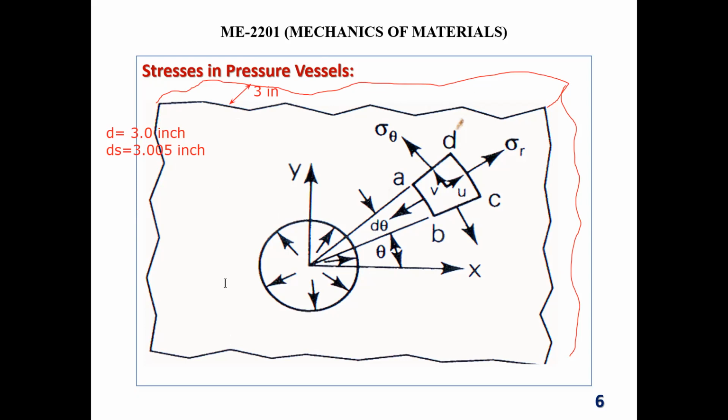You are just putting it in the hole, and on the other side you are hammering a little bit to try to insert that bush or shaft within the hole. Then you need to realize what kind of things might happen there. Number one, if the material of the plate is a little bit softer than the shaft, then what will happen? The diameter of the hole might increase, and it will let the shaft inside the hole, right? So in that case, the diameter will increase.